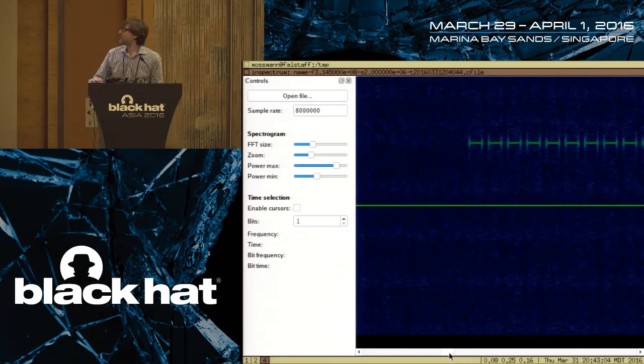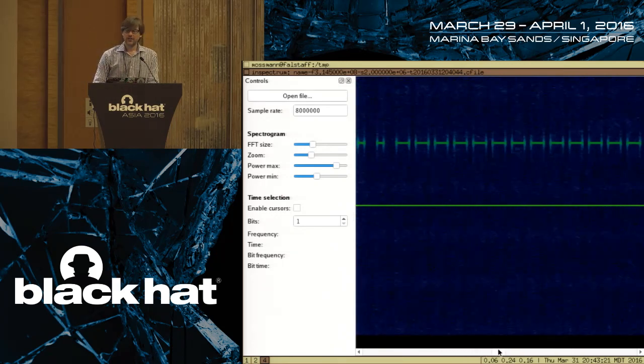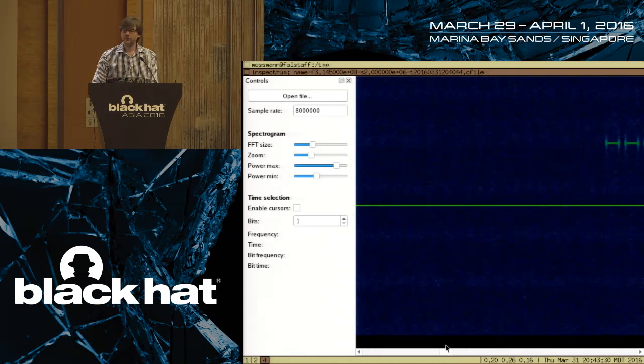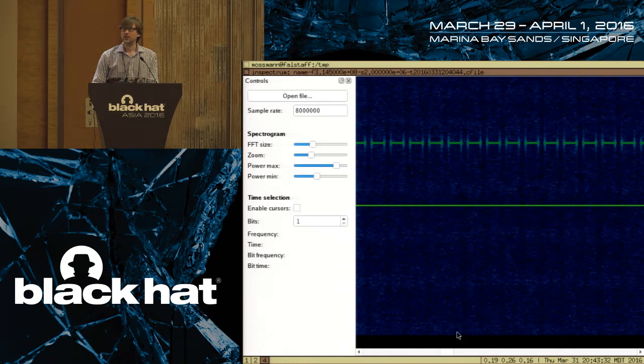They kind of look like an I-beam, or like a capital letter I turned on its side, because there's a little bit of frequency spreading when there's this abrupt on-off transition. This signal is turning on or off. But you'll notice if you look horizontally, if I scroll through here, do you see how everything is all lined up horizontally? They're all at the same frequency. Every single pulse is at the same frequency, which tells me this is not a frequency modulation. But the amplitude changes. The amplitude is represented by the color.